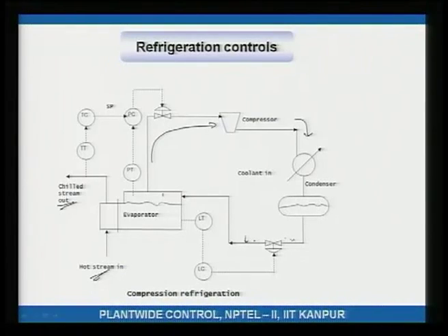That large pressure drop causes Joule-Thomson cooling, and because of that you may see that around the regulator some ice forms. This you may have observed. Something similar goes on here. There is a large pressure drop across the valve, and as material flows across this valve, it partially vaporizes and cools off because of the Joule-Thomson effect. Okay. That vapor liquid mixture accumulates in this evaporator.